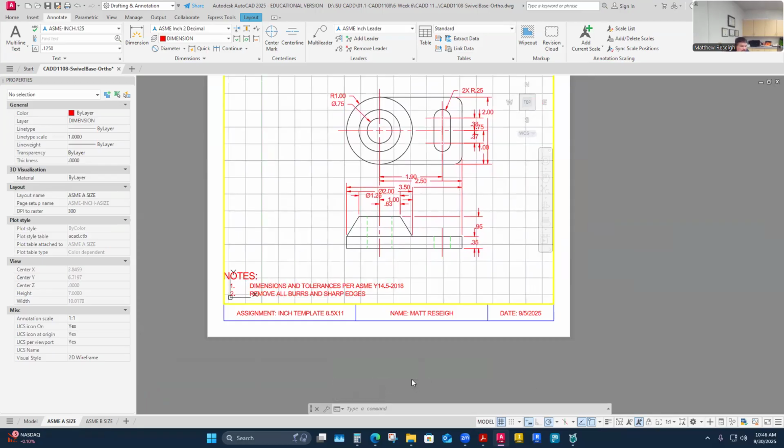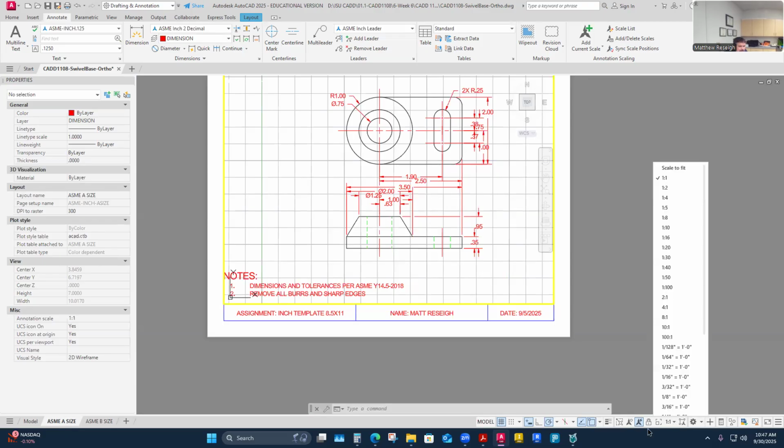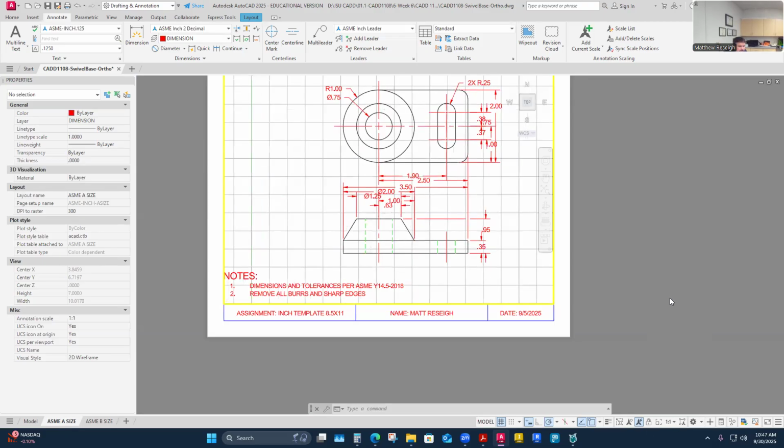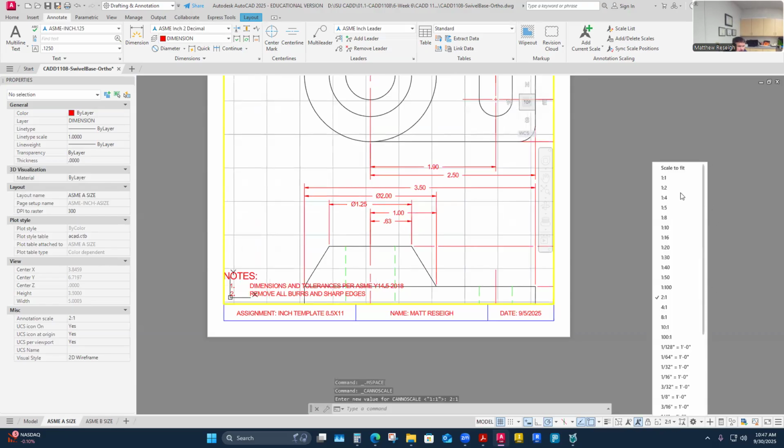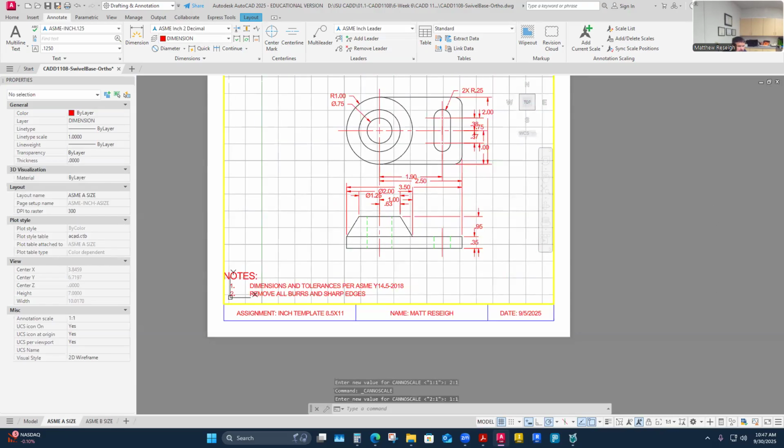Yeah, the only problem I have, so what am I? I'm a 1-to-1 on a size. It's a good size of sheet. I have an issue where I'm crowding my dimensions. So I think I'll copy and move them, and I'll have to use two viewports to fix that, right? For me to do some cleanup here, and maybe I'll flex these. I unlock them to flex them, and I might just jump this up to 2 and then jump this back to 1. I just want to make sure my dimensions are auto adjusting how they fit. They're a little crowded. My dimensions are going to be a little crowded here. They're not super clean, right?